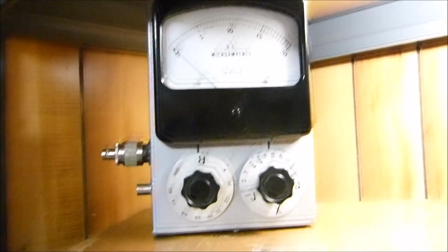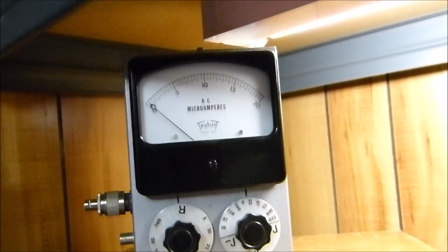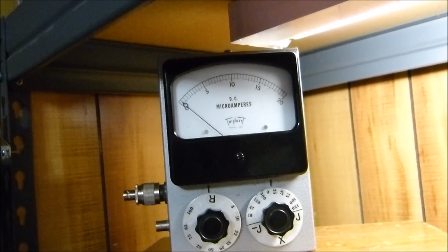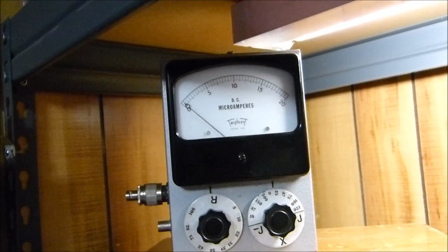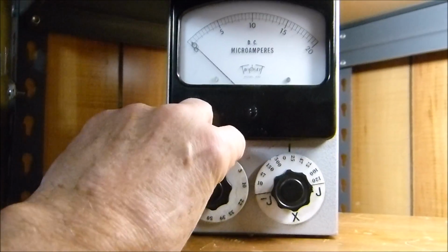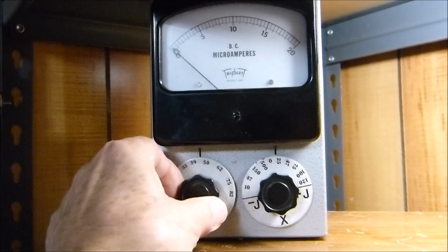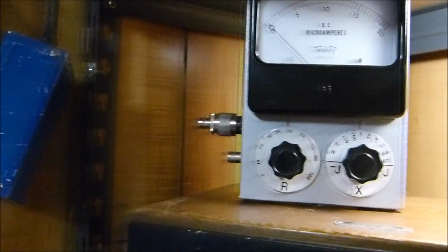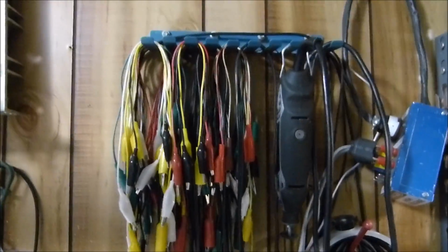Here's some homebrew devices I've built and have used. RX bridges. Works real well, up to about 20 megahertz. Above that, the stray R and C and all that stuff in there gets a little weird, and it doesn't work as accurate up there. You know, just junk that you have to live with.